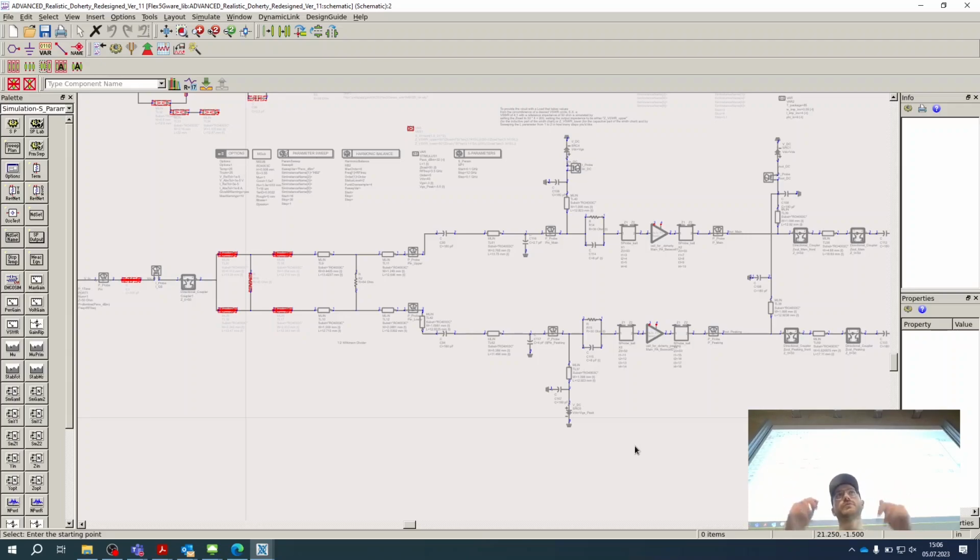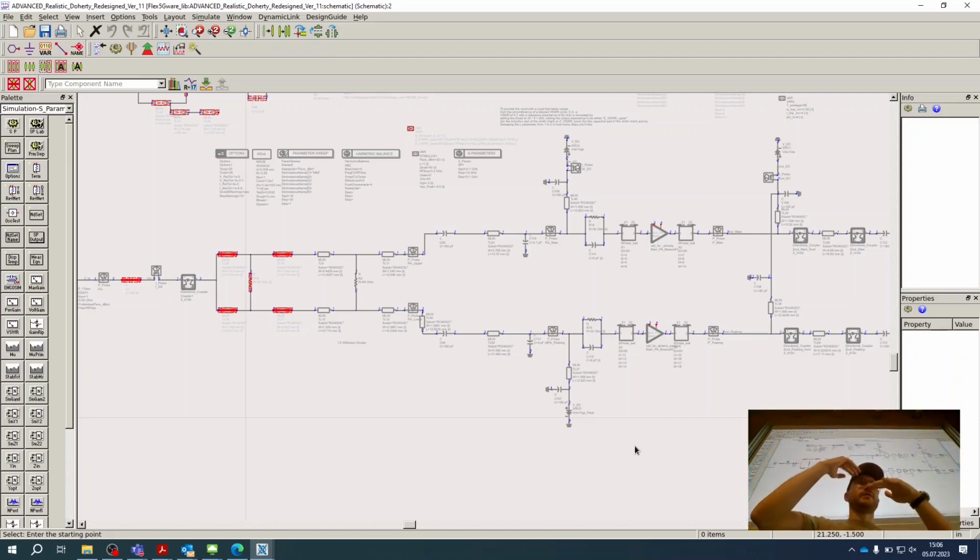What does that refer to? It refers to basically the amount of energy that a carrier in the valence band has to absorb in order to move to the conduction band, the band gap. Thus this 1.4 till 4 electron volts. We wanted these materials. Why? Because these materials have the property that we're able to apply a larger drain source voltage on them.